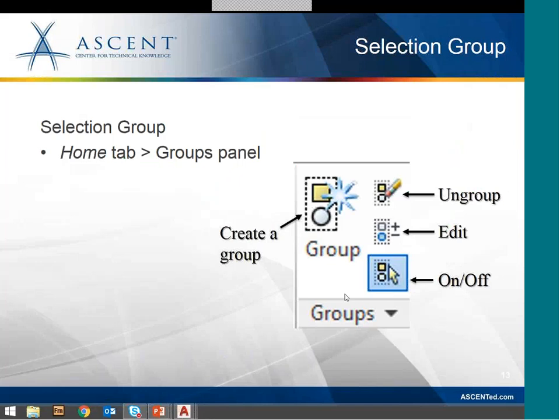Okay, so I'm seeing from Norman, he uses Civil 3D, and he has to use the classic group command rather than a group command because it's not available. You can try typing group into the command line and see if that works because it should still be available in the software. So Hector says, yes, this is going to be very helpful for him. Steve says, not very often, but could be useful.